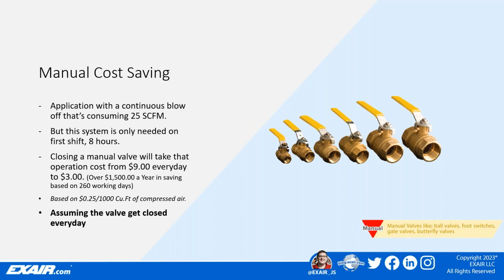For example, ball valves work great for applications like this. A customer with an operation where they are using a small air nozzle to help parts move as they process around a vibratory bowl feeder. The operation, though, was only used for 8 hours on first shift. The customer figured out this operation was blowing 24/7 when they had an overnight maintenance shutdown and heard it blowing freely while the operation and production line was down.